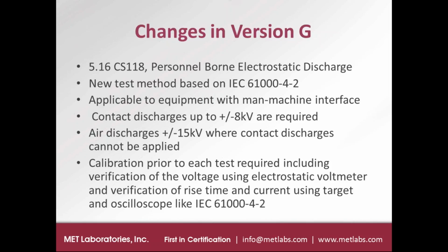And it's applicable to equipment that has any man-machine interface. So any equipment that a human would normally have to touch in order to operate it, their body could discharge to that electronic equipment. And so the standard requires contact discharges up to plus and minus 8,000 volts, and wherever contact discharges can't be applied, air discharges up to plus and minus 15,000 volts.